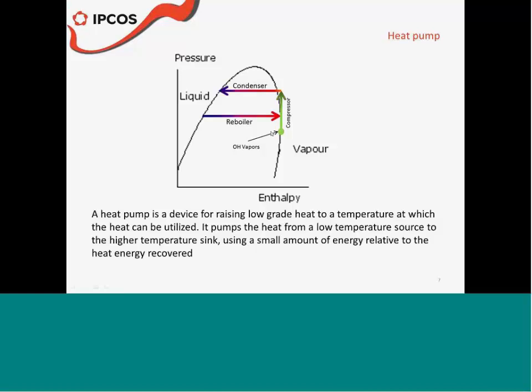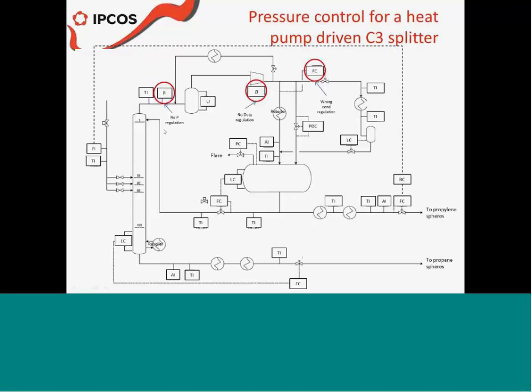So it's basically using all this latent heat, but now at a higher temperature, enabling it to heat the reboiler of the very column. This is what is shown here. If you see, the overhead vapors are compressed and sent partly to the reboiler. This reboiler and this reboiler are the same, just a matter of the graph to make it a bit more clear. It's the same heat exchanger, and then you use the compressed vapors to give duty to the column.